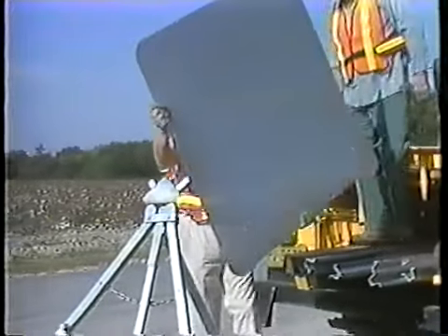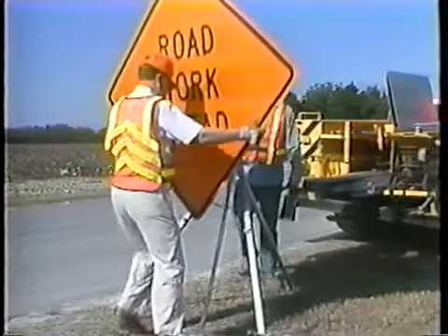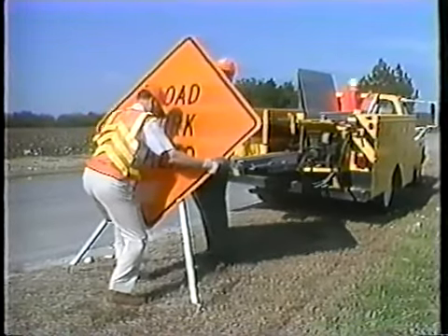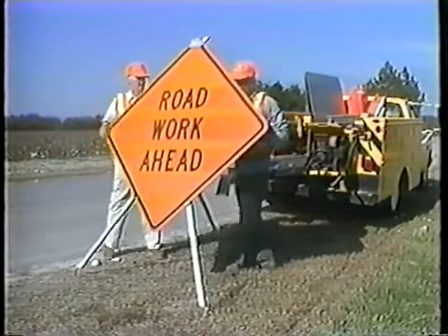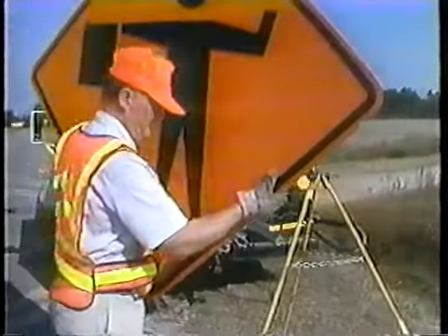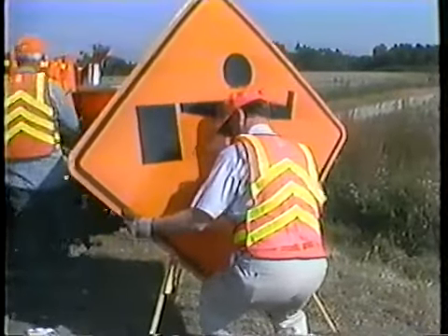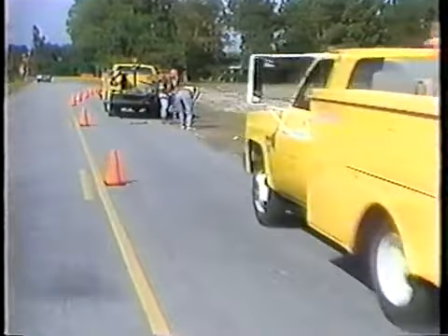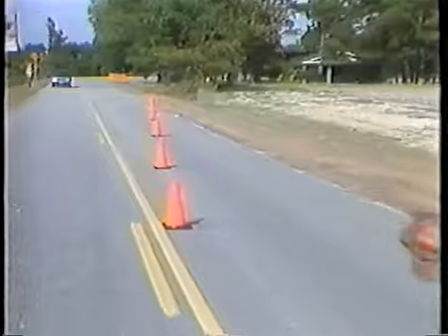You are probably most vulnerable during the installation of the traffic control devices. To minimize this hazard, install the devices before work begins, starting with the first device the driver will see when approaching the area. Then continue installing devices, advancing toward the work area. To evaluate any work zone traffic control, drive through the work zone after all the devices are in place.